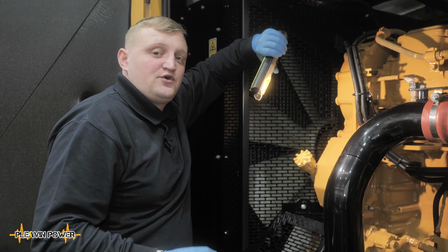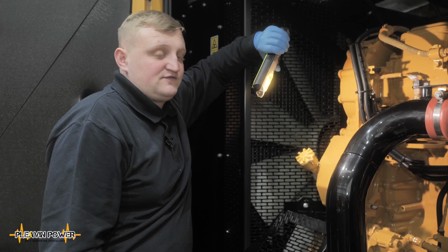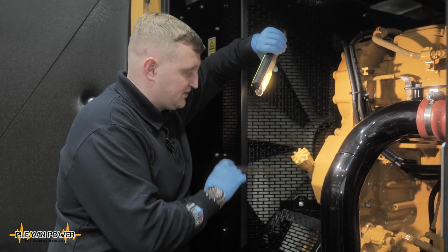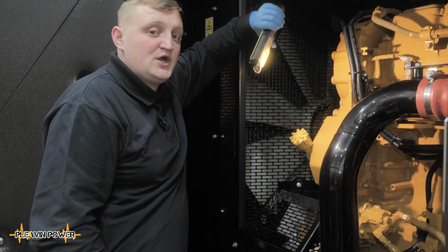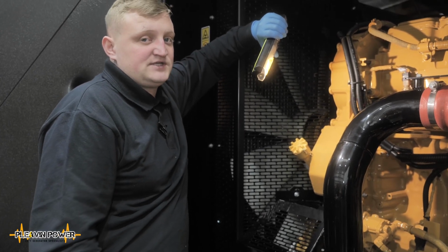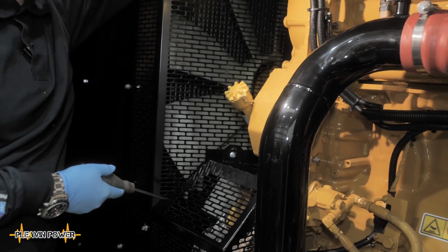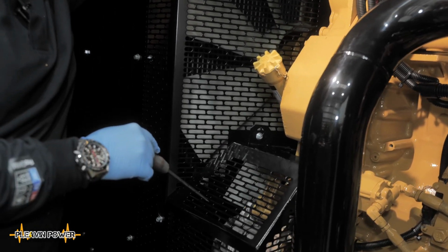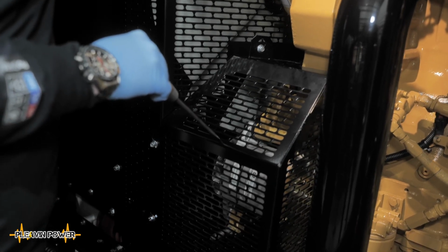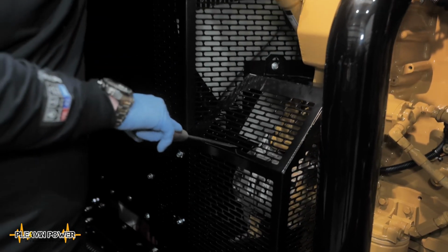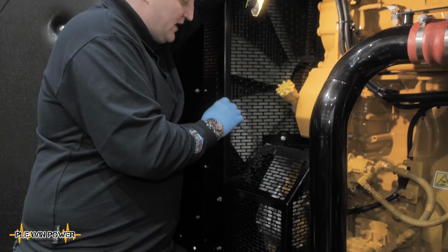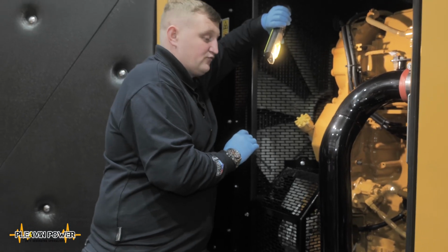Another thing that's often missed during a routine major or minor service visit is the fact that these charge alternator belts and fan belts deteriorate over time. We normally change belts during service visits in most scenarios where these belts have got the original paint marks on them from the factory, and unfortunately these need to be changed at least every 2 to 3 years as per the OEM specification. Why, you may ask? These belts are made of rubber, and whilst it's durable rubber, the rubber doesn't last forever.